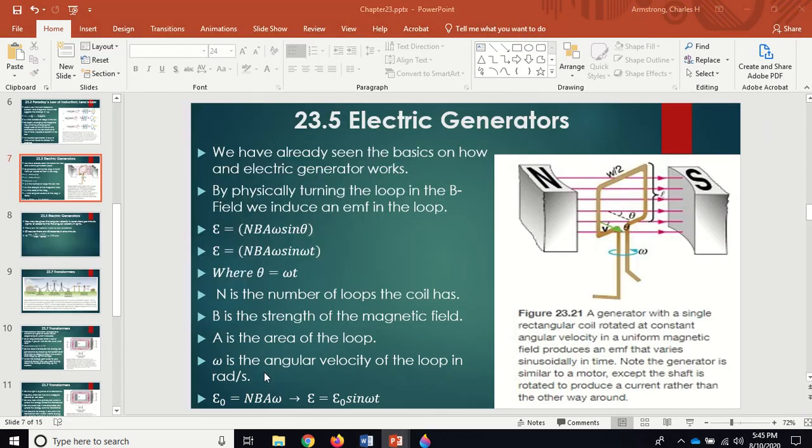Again, you want 0.426 Teslas here because this goes from being parallel to the field, in which no flux passes through it, to being perpendicular where all the flux passes through it.